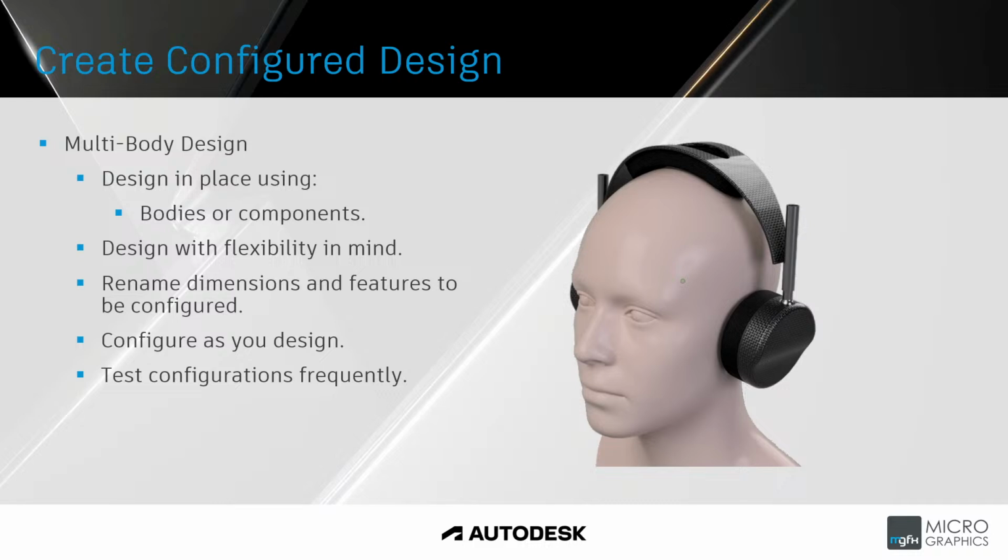It's just a lot easier to keep track of the things that you want to change, rather than going back later and trying to find it in the configuration, or trying to find it in your timeline to then capture as a configuration or configurable object. And then also test your configurations frequently. Go and switch between configurations to try them out.